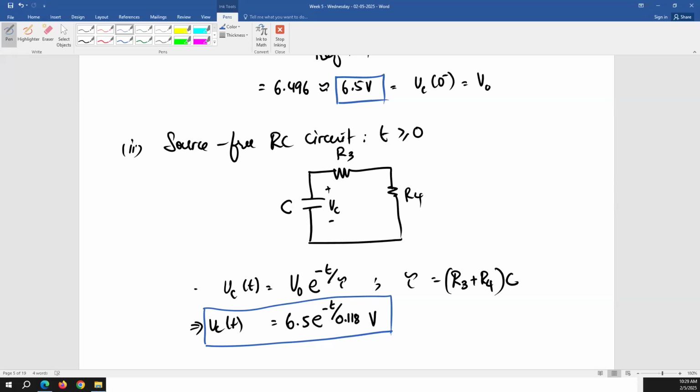And then even if you make the RC time constant large enough such that it won't even discharge, or discharges so little that it's negligible until the next peak arrives, then it's going to become pretty much a constant DC waveform. So there's a whole game of the time constant over there.